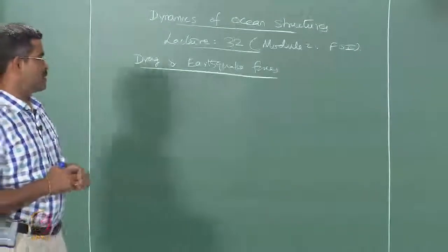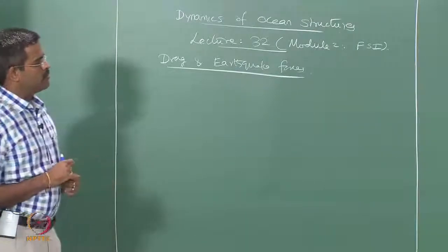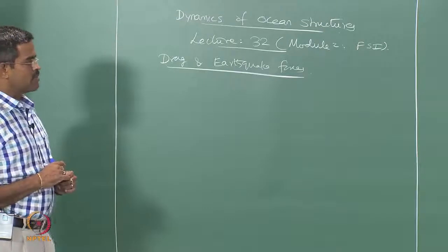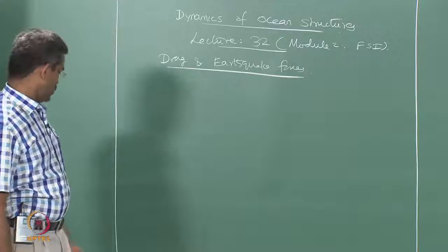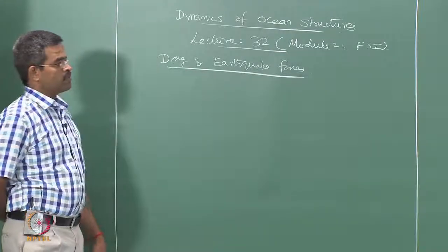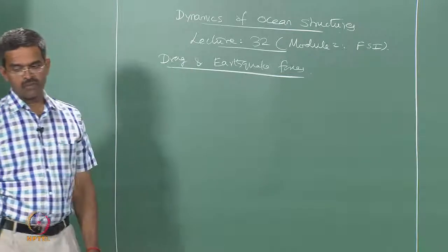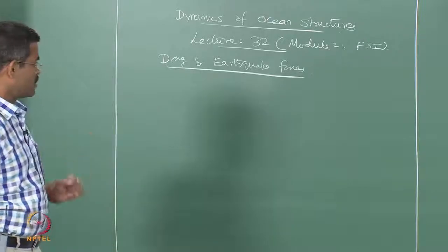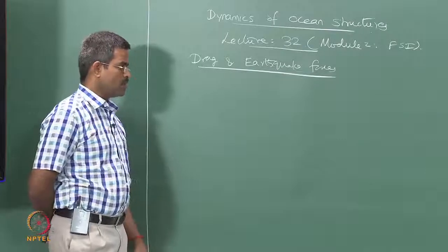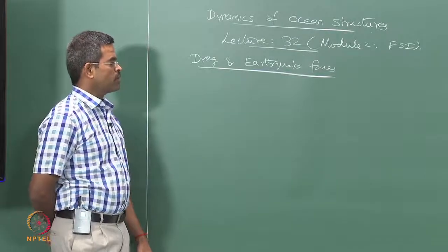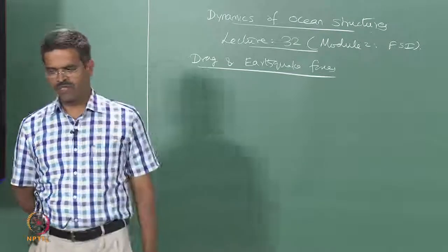So, in the last lectures we discussed the influence on water particle kinematics, on velocity variation and the flow field, and the variations caused by interference from the cylinder, which is blocking the wave field. We have also seen the influence of current on the velocity profile variation along the depth. We have also seen the secondary vibrations caused by a cylinder, kept horizontal or vertical, what we call the characteristic dimension of the cylinder in the wave approach angle, and we understood how the water particle kinematics gets altered.